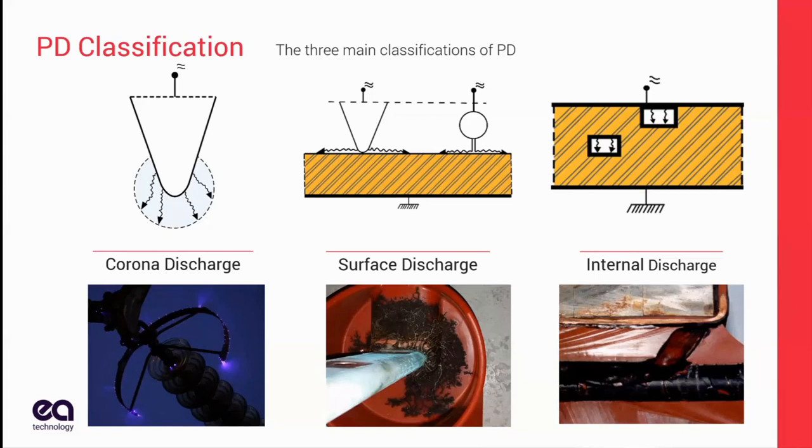So when you get into the EHV transmission lines and insulators, without a perfectly uniform field, there are spots on that conductor where air molecules will not be able to withstand the field.